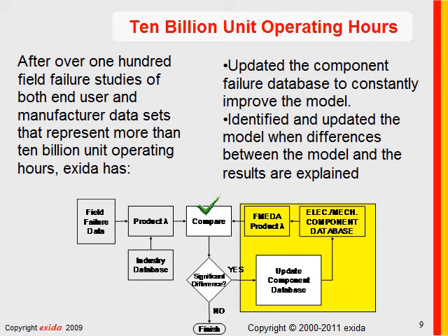If we have a product level failure rate that comes from an FMEDA and field failure data for a similar product, obviously, you can learn something by comparing these numbers. I mean, they're supposed to match, right? And what happens if they don't match? If there's a significant difference, we must find the reason.